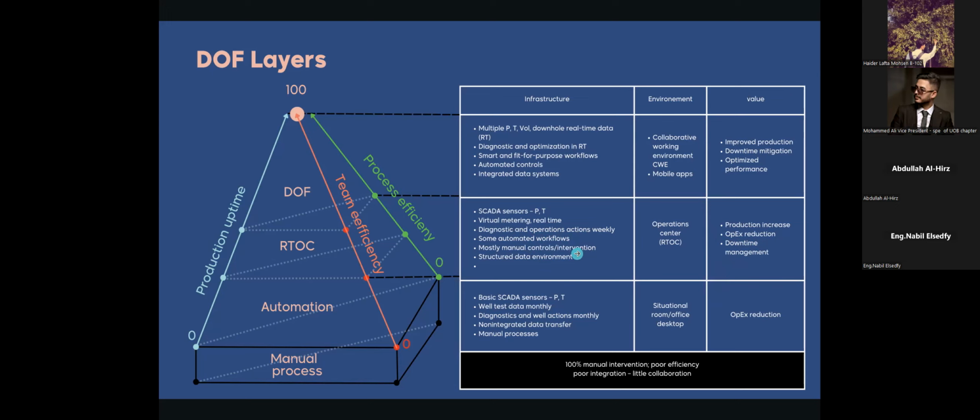Then you can put a proper workover plan to bring that well back into production. Maybe if your well is on natural flow, the model can tell you directly that you need to run an ESP to produce it. Or maybe you need to re-perforate. Maybe you need to optimize your choke setting, or do a stimulation based on the pressure and temperature and all the data coming from the well to the operation center.